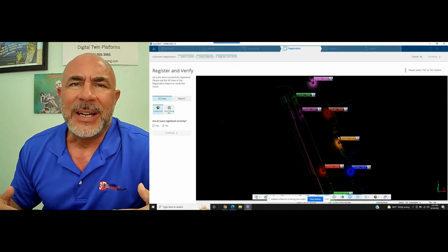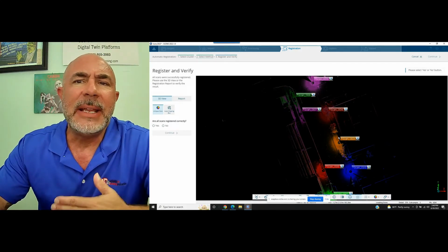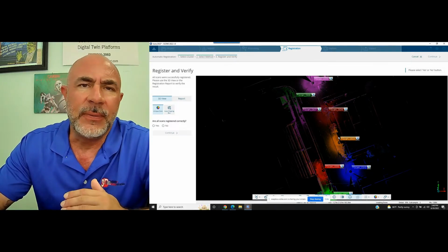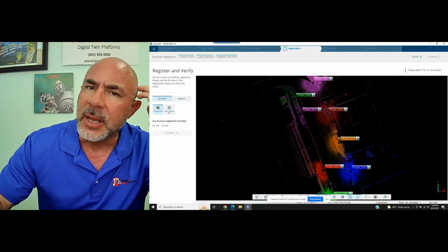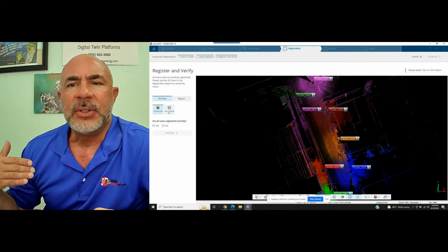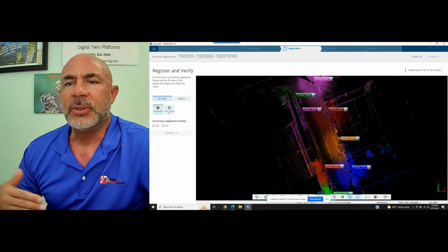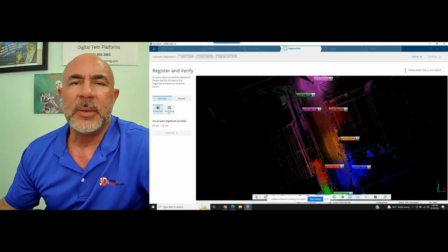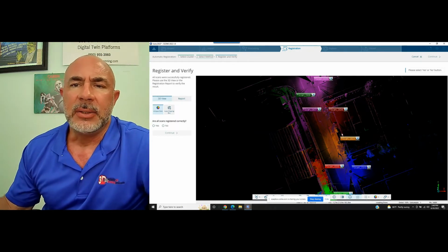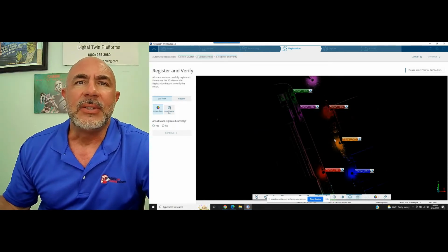So, you get an X330 unit and it has 330 meters of range. That first 80 feet or so of range is where you get the 1 to 5 millimeters in accuracy, 2 to 5, 1 to 4, depending on the machine that you're using into the S series. And so that means that, if you're scanning down the side of a building, just because you get 330 meters of range, you don't scan on one side of the building and then go 300 meters to the other side and scan again. You're going to need to step that scanner through that sort of distance because, again, the first 80 feet is where the accuracy is.